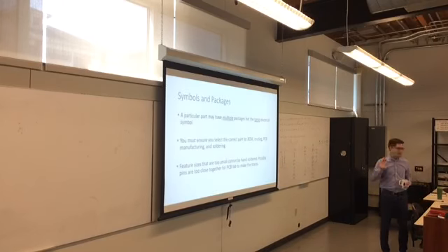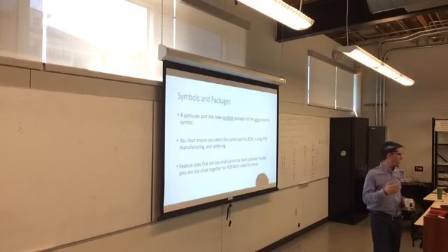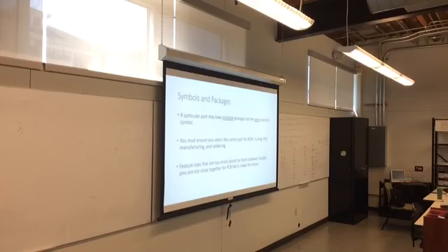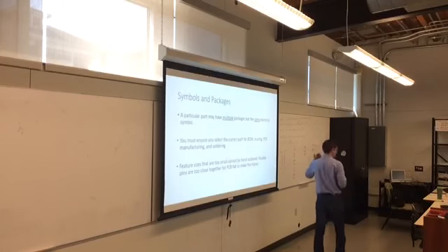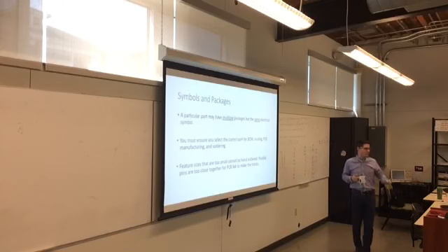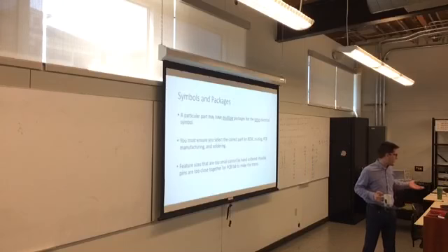So, a particular chip may have multiple packages, but the symbol looks exactly the same. Make sure that when you pick an object from whatever tool, whatever library you're using, you get the one with the correct package. It matters for routing. It matters when you go to DigiKey and you order the same part. With the students here, with them ordering all of their Atmel 32U4s, there are 3 or 4 different package types. If they just type in 32U4 and order a bunch of them, they can get chips that just don't work or don't fit.